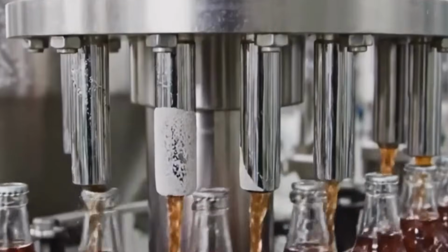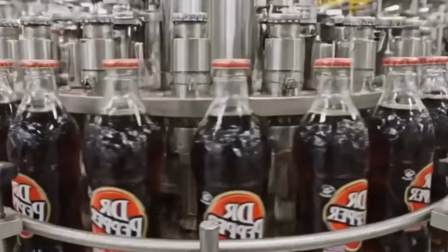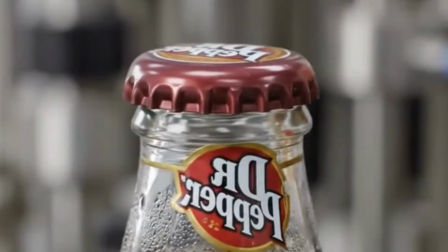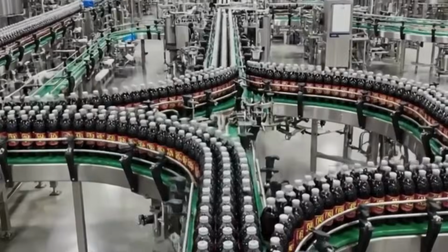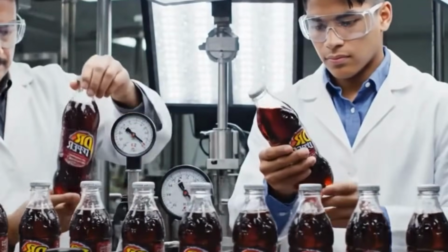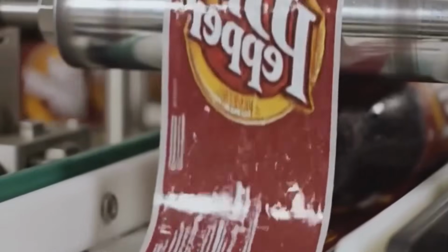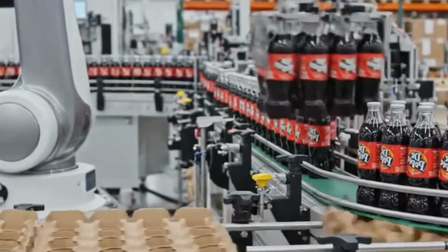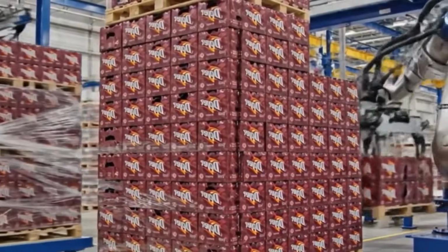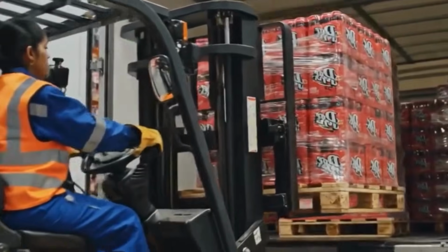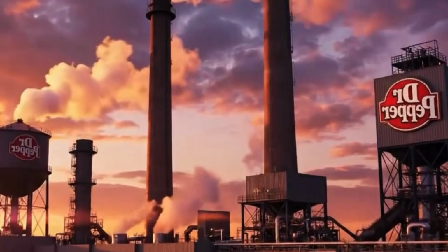Finished multi-packs are conveyed toward case packing stations. Corrugated cartons are erected from flat blanks by automated formers and transported via belt to loading stations. Pneumatic pushers slide each multi-pack into its case. In robotic systems, Delta robots or articulated arms equipped with suction grippers lift and place products with extreme precision, adjusting in real time for orientation variances detected by machine vision.